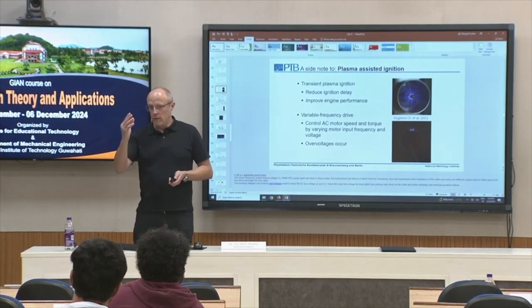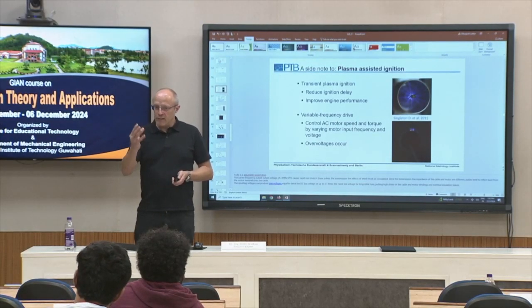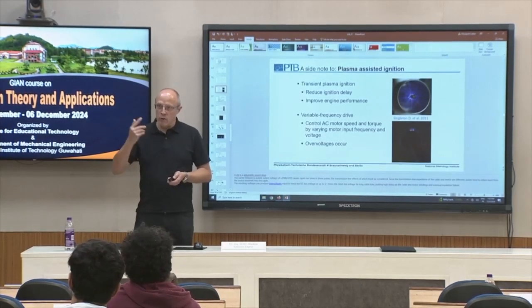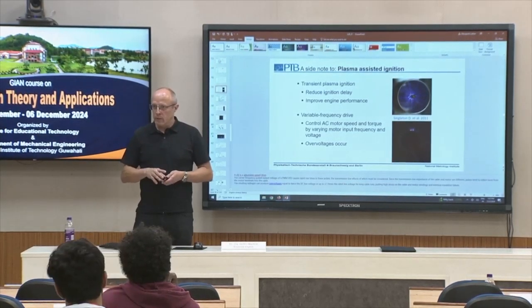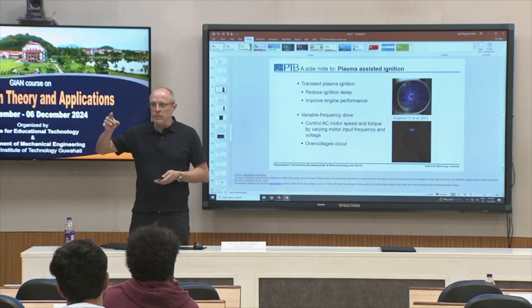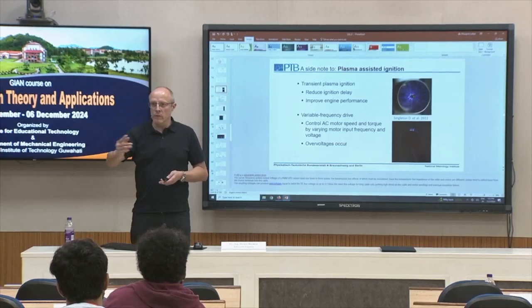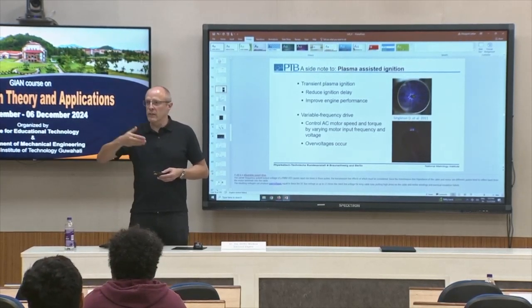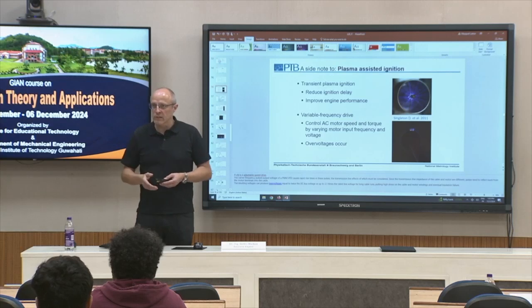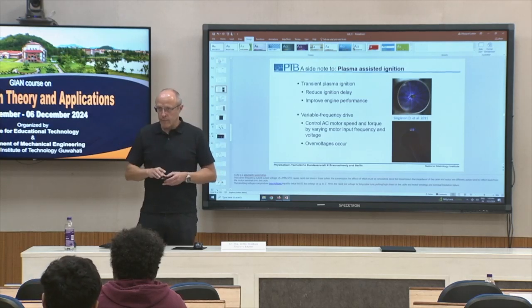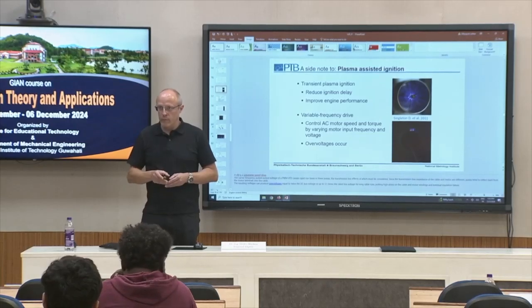In your combustion volume, you have of course a very strong turbulent field, so you have your spark and maybe a local ignition, but then you have an extinction. With these lean conditions, the temperature is not so high, the velocity is not so high, and so on.